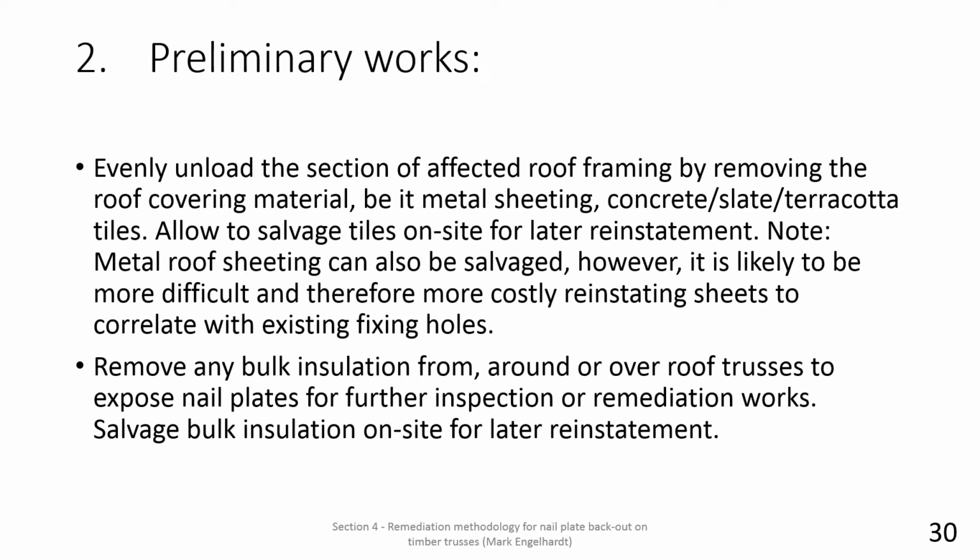A remediation scope of work is likely to entail preliminary works whereby roof coverings and other removable load items are evenly removed, unloading the subject defective trusses.